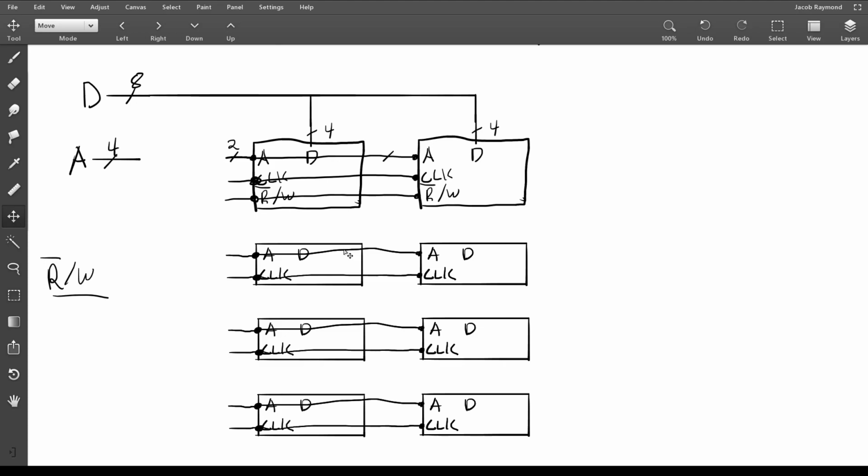All right. So why have I created 4 of these? Well, if we think of it, each of these banks here can now support 4 different addresses, the same as above, right? Because there's a 4-bit location here, there's 4 4-bit locations, and we've combined them sideways in order to create 4 8-bit locations.